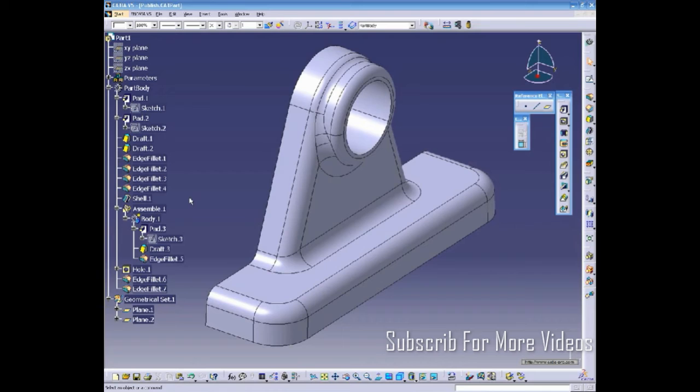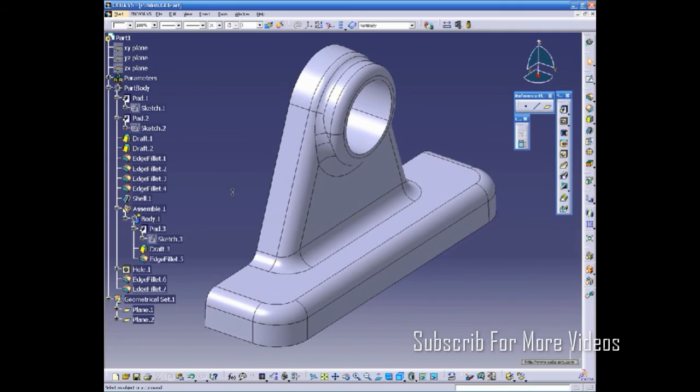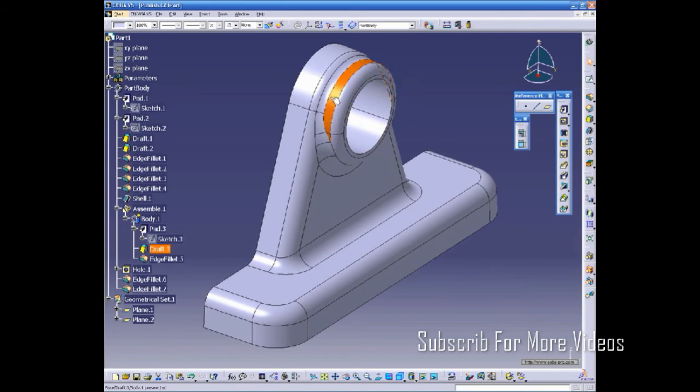Okay then, let's see the benefits behind using these kinds of folders. Starting with bodies. We use these types in order to simplify the complex design. As you see here, this side is the most difficult one in creating this part. Then to make it easy to be done, the easy portions are produced inside one body, called part body, while the difficult ones are created separately in body 1, and then assembled to the first body.